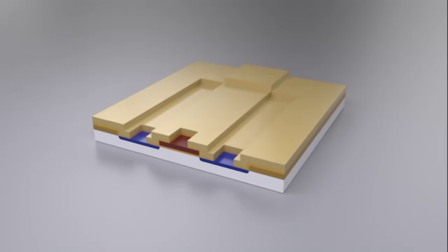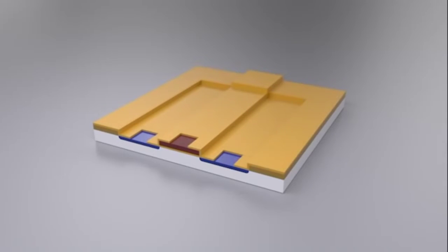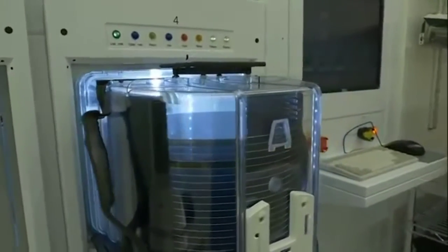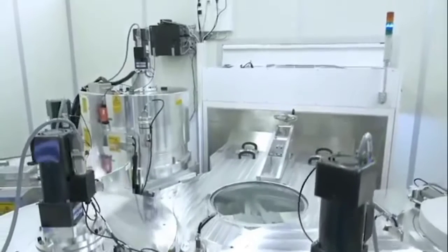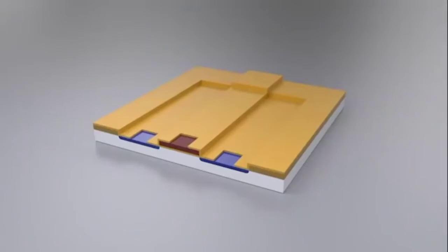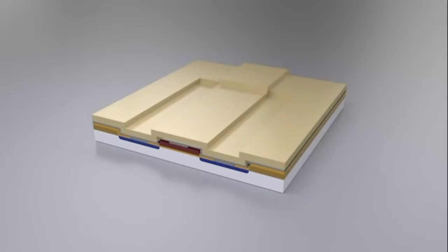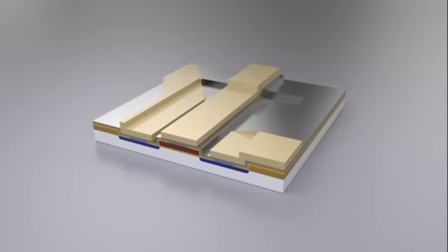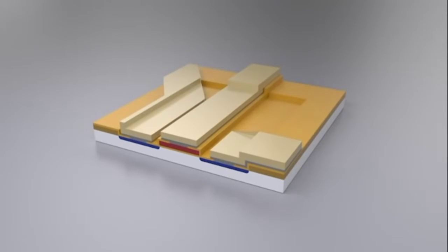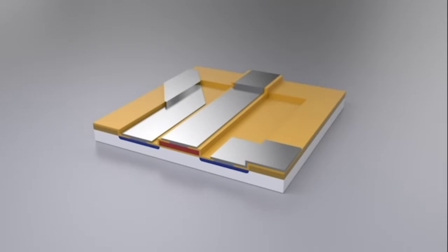Contact holes are etched to provide access to the conductive layers, enabling the contacts and interconnections to be integrated in the wafer. This is done by depositing metal alloys onto the wafer in sputtering machines. Once again, the photoresist and mask are applied. The unexposed strips remain as is after the etching process, providing a point of contact to the underlying layers. To give the insulation layer above the interconnections the smooth finish it requires, a chemical-mechanical process is used to polish away excess material with micrometer accuracy.